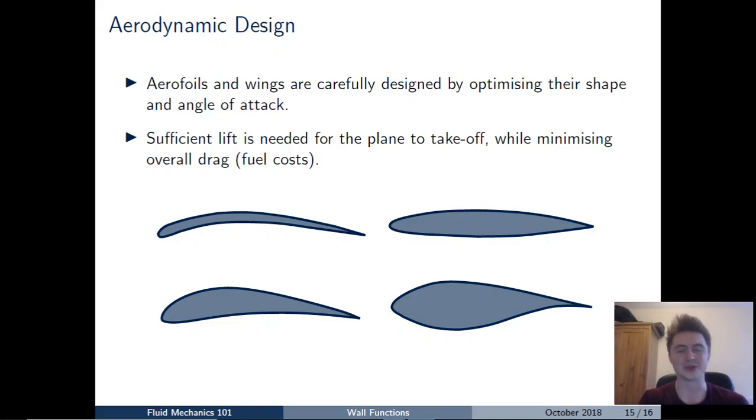At this point, it's also worth considering that the shape of the aerofoil, as well as the flow direction, has a significant effect on the shape and the magnitude of that pressure distribution on the top and bottom surfaces of the aerofoil, and therefore also on the lift and drag that the aerofoil develops. And what we find is that the aerofoil shapes that tend to be used can be significantly different depending on the application that we're using the aerofoils for.